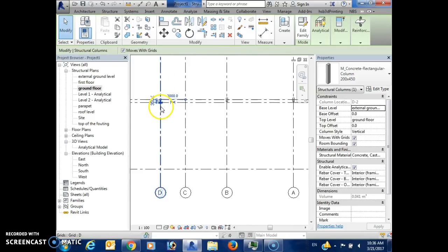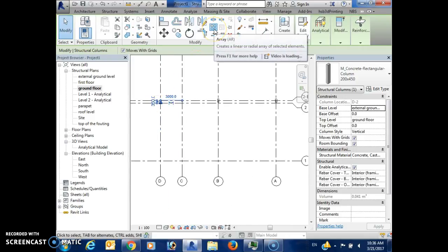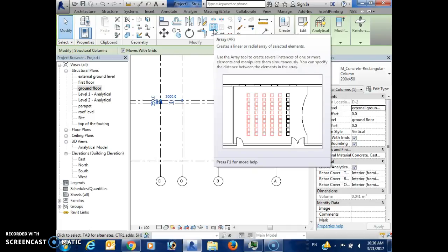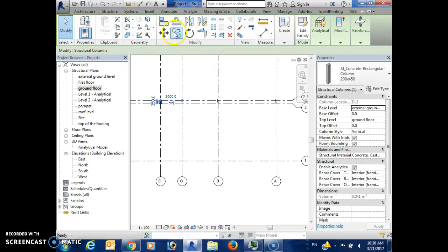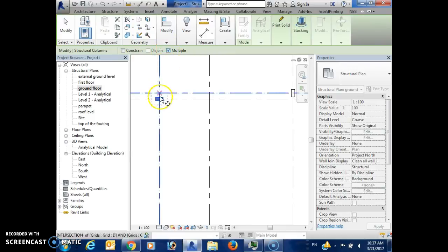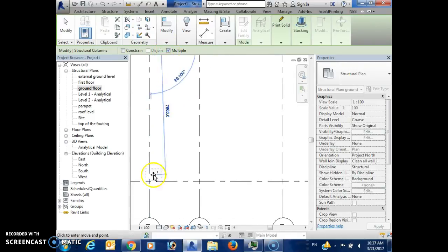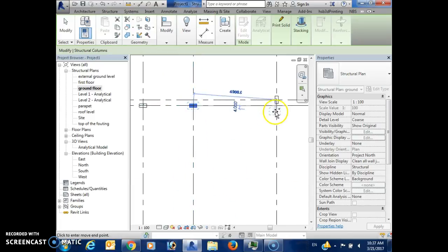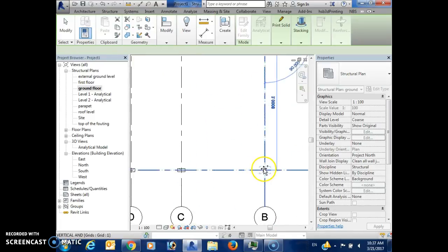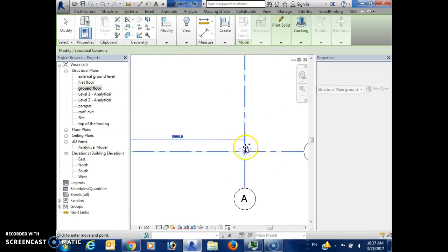Okay? And I'm gonna copy them now. I can do it by copy, or I can do it by array. You've got the array explained in the videos that I have on YouTube. As today we have to finish the whole project, I'm going to explain only copy. If you wish, in the next class I will explain array. Okay, so now with copy we select multiple, and I'm gonna copy my column at all the places, in all the intersections of my grid.